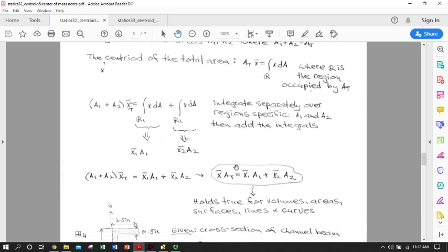So if we have a simple shape, we can say the centroid of that shape is equal to the centroid of maybe another simple shape, subtract them, and get the area of maybe a complex difference that we wouldn't have wanted to integrate. Or vice versa, if we have a whole bunch of simple shapes with easy to find centroids versus some coordinate system, all we have to do is multiply those areas times those simple, maybe by observation, individual centroids, add up the products, divide by the total area, boom. We have the x or y centroid of what otherwise would have been something way more complex to integrate than we wanted.